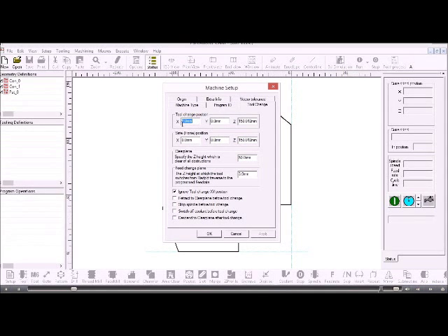So the XY tool change position and the home position can be at 0, but the Z value should not be at 0. 0, as far as Part Master is concerned, is the top of the job. So we need to set the tool change and this home position as being a value above there. So normally that should be quite a large value, but of course the actual value will depend on the travel that you've got on the machine.